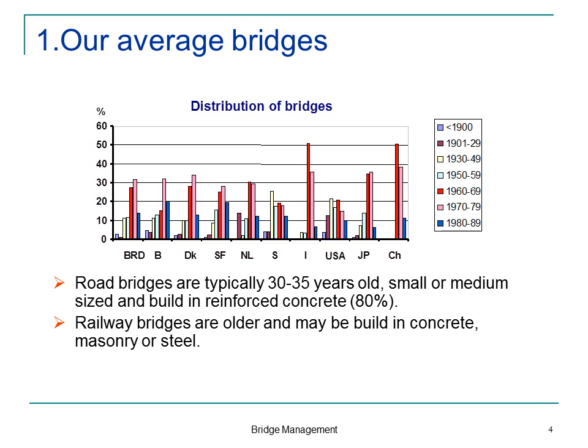The deterioration starts at day one, but after a number of years, the salt will have reached the reinforcement and start corrosion, and the paint on the steel superstructure will start to fail, and that will lead to corrosion. So 25 to 30 years, that's typically where you start to see the problems.